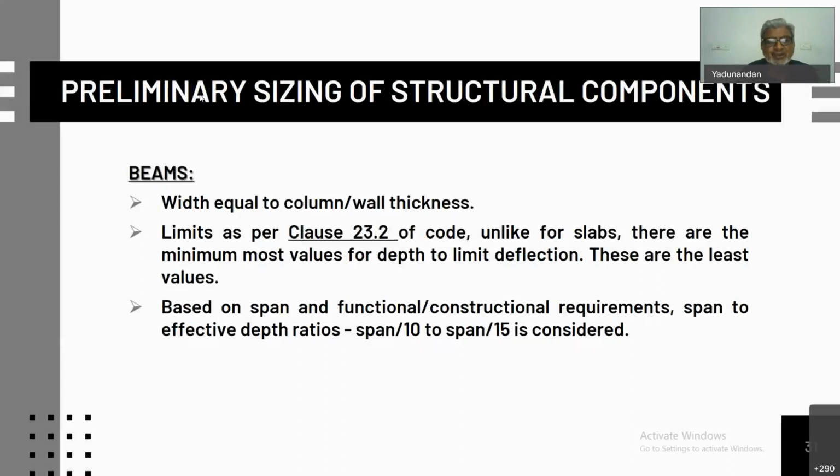If you consider next, go to the beams. There is a limitation, but anyway, in the slabs, it's also there that way. You may get various spans and various thicknesses. You will have to reduce the types of thicknesses of the slab over the area to a minimum of 2 thickness values like that. You just cannot go on providing different thicknesses for different slab regions.